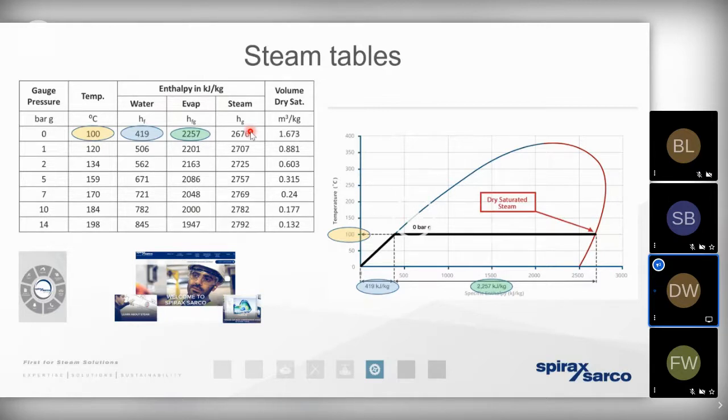So if you think back to the presentation we went through 2 weeks ago, if for any reason our client wasn't on top of the boiler controls or the steam generation in the boiler house, we'd have wet steam. If the energy source, if the fuel was contaminated, we'd have wet steam. So we could be at risk of failing to put the required amount of energy into that steam to make it fully evaporate. In other words, the steam that is generated could be wet, and also it would fail to be saturated with energy. So it would actually exist at this point here on the curve. That's going to cause us a number of problems because we've got wet steam now.